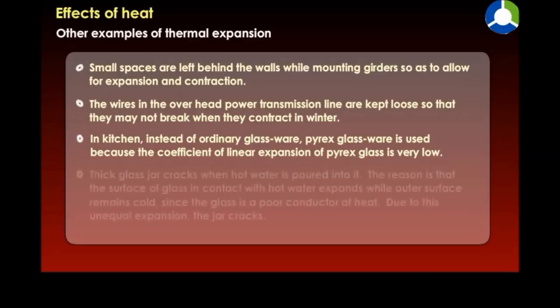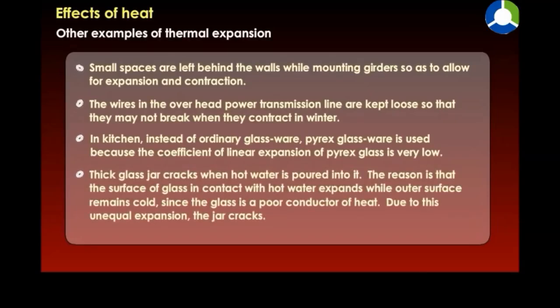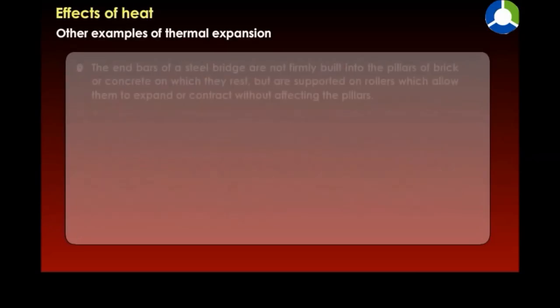Thick glass jar cracks when hot water is poured into it. The reason is that the surface of glass in contact with hot water expands while the outer surface remains cold, since glass is a poor conductor of heat. Due to this unequal expansion, the jar cracks.